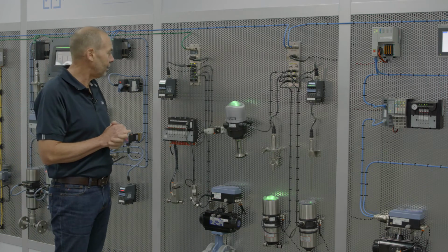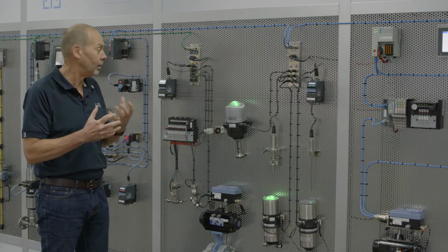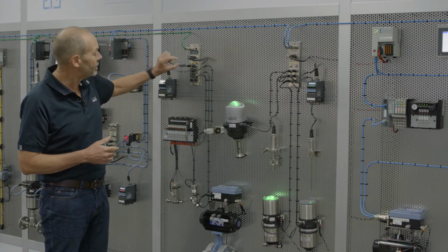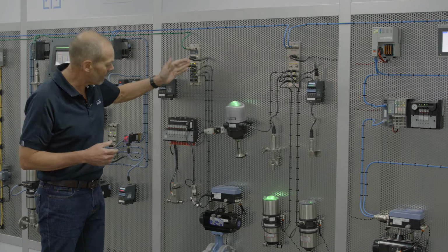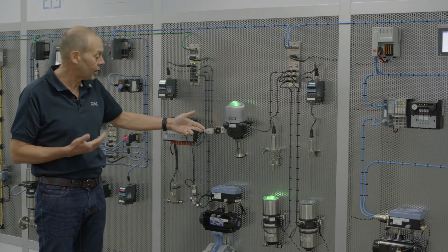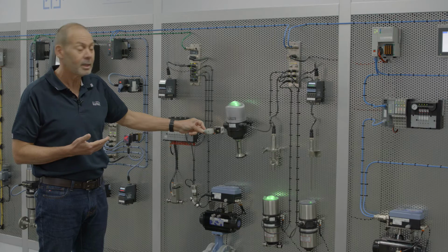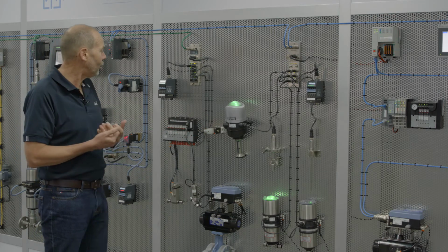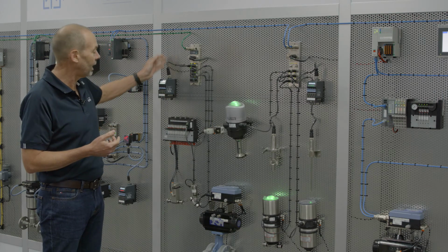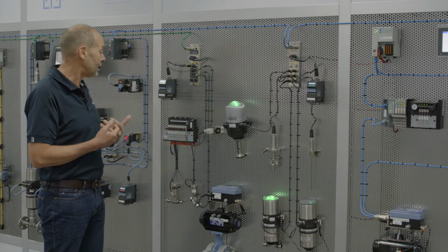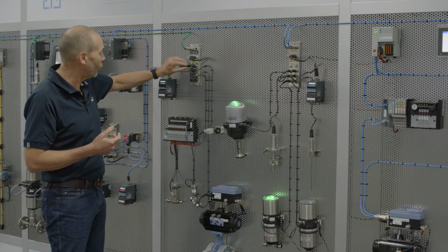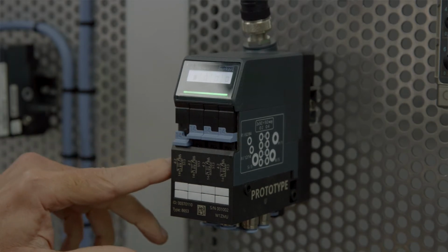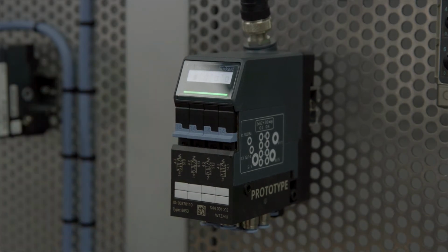These ports are also quite functionally capable in that they can be set up as just a digital output. In other words, this first port is connected here just to a solenoid valve in 24 volts DC, so it's operating just as a traditional I/O block. However, the ports can also talk digital communications to the devices in the field. As an example, a similar IO-Link port in this instance is talking to a block that has 4 valves in there controlling actuators in the field.